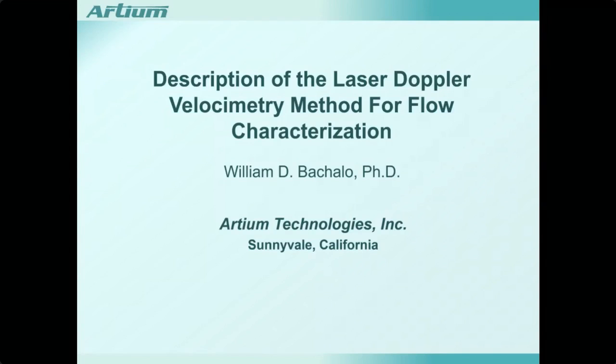This talk is going to be, as Sanjit pointed out, describing laser Doppler velocimetry. And I thought before I get started, I should try to avoid some possible confusion by mentioning that Europeans generally call this method laser Doppler anemometry, or LDA. They apparently don't understand the meaning of anemometry. Anemometry refers to measuring wind speed. LDV instruments can measure gas and liquid flows as well as surface speed, so we refer to this device as a velocimeter rather than an anemometer.